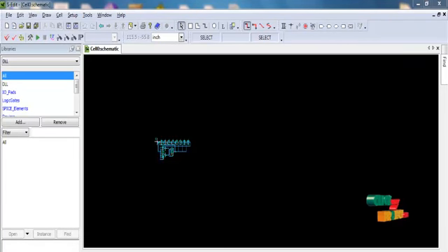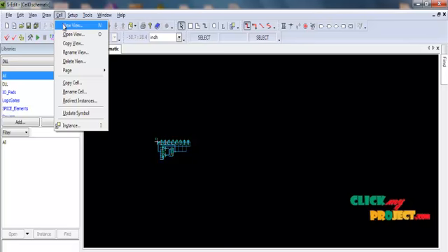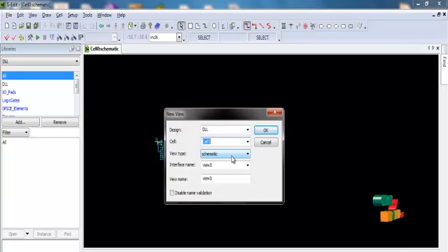Now we are going to discuss the running procedure of our product. Our product can be implemented in Tanner EDA version 13.0. Open the tool window to create a new file from the file menu. After creating the file, add the library from the add option. After adding the libraries, create a new cell from the cell menu, using new view to create a new cell.